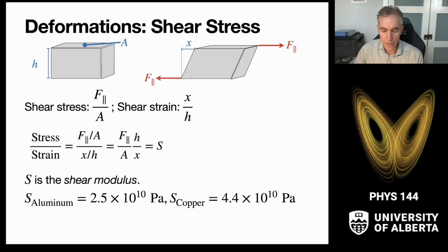The final type of stress that we want to talk about is called a shear stress. And that's summarized in this diagram here, where we think about a three-dimensional object that, instead of pressing on opposite sides or from all sides at once, we think about what happens if we pull on the top while pushing on the bottom. So this is called a shear force, where as you move vertically, you have changing horizontal forces. So a shear is usually, as you move in one direction, there's a change in the perpendicular direction.